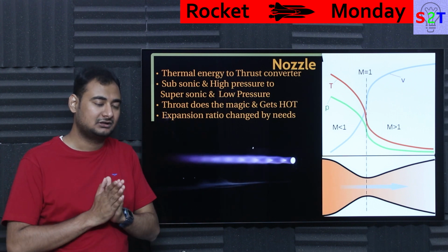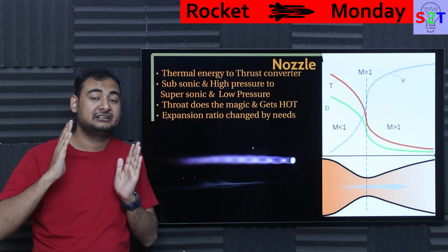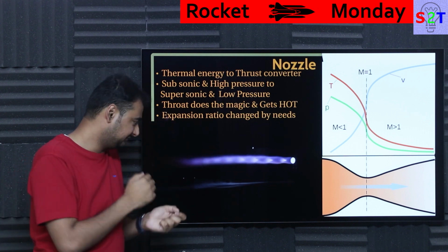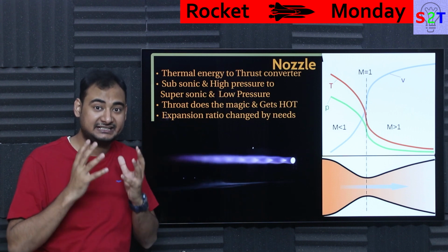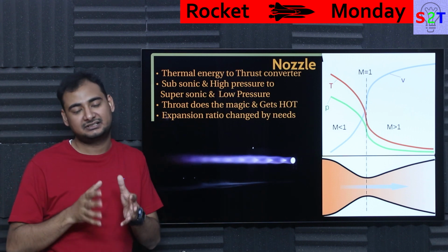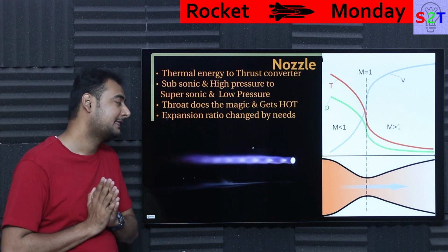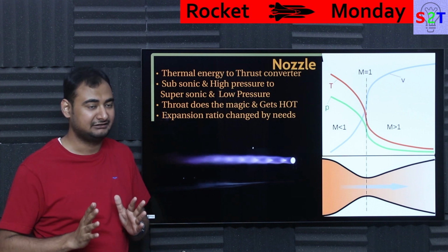That could create what we call flow separation, meaning your hot gases can be separated from the wall. That could create very severe oscillation. You will never have a stable flow; physics does not allow that. There is inherent chaos there. So in that sort of scenario, you can literally have oscillations, and those oscillations could get so brutal they could destroy your engine. So generally, flow separation is not something that you want to have ever.